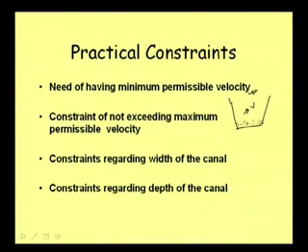If it is a plain area, of course, in the city if it is hill, that is fine, velocity may be high, but if it is a plain area, then the velocity drops below a particular limit, and depending on the size of the sediment, it may start settling there. If it settles, then the carrying capacity of the canal will be reduced.